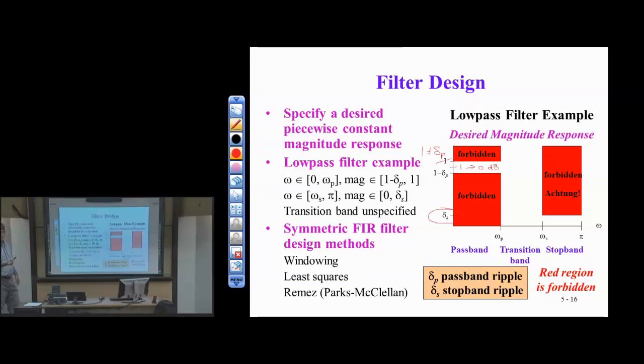Okay, now problem 2.2, you are designing a low-pass filter. And then the ripple, if I tell you the ripple is 1 dB, it means that this interval is plus or minus 1 dB. So I go from minus 1 dB to 1 dB when designing the filter. And I'll give you an example of that in just a second. And again, the transition band remains unspecified, but you should sanity check what you get back to make sure that what happens in the transition band does not exceed 1. I'll give you examples later in lecture 6 that we'll see that doesn't hold.